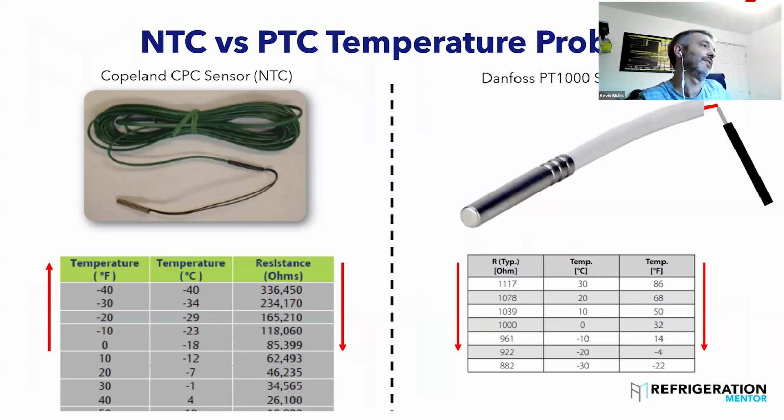Obviously, a quick check for you, if you haven't got the table to hand: if your case is off, let's say, and it's all at 10 degrees C, all your probes are going to have roughly the same resistance on them. If you've got 3, let's say, at 1,040 ohms, something like that, and you've got one at 1,500 or one at 3,000, that probe is almost certainly going to be faulty because everything's at roughly the same temperature. They should all be saying the same thing.